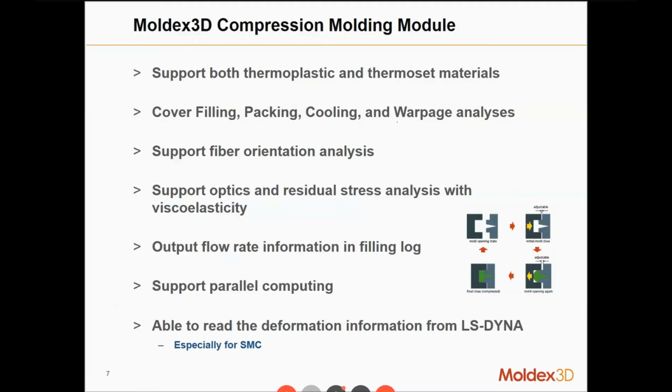And Moldex3D supports parallel computing. This can greatly enhance our calculation performance, which means we'll require a much shorter calculation time if we use multiple cores of the computer to do the calculation. And finally, Moldex3D is capable of reading the deformation information from LS-DYNA. And this is especially for sheet molding compound. Because for SMC, the beginning stage of a compression is more like the polymer is still at a solid stage. Now, Moldex3D is specialized and very powerful in fluid dynamic wise calculation.